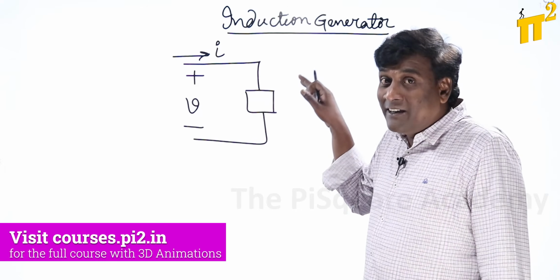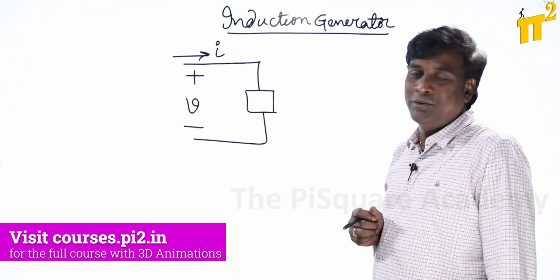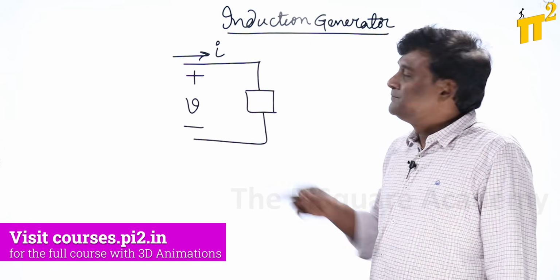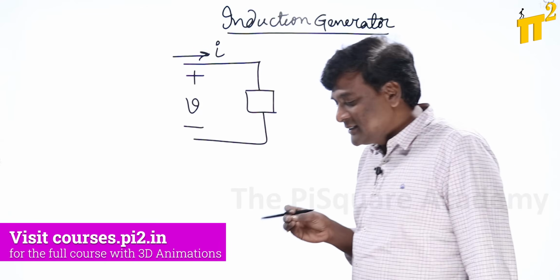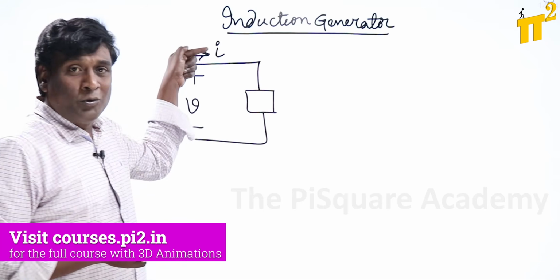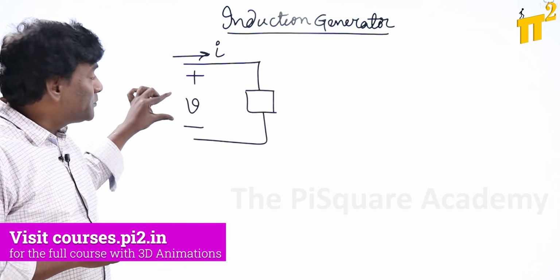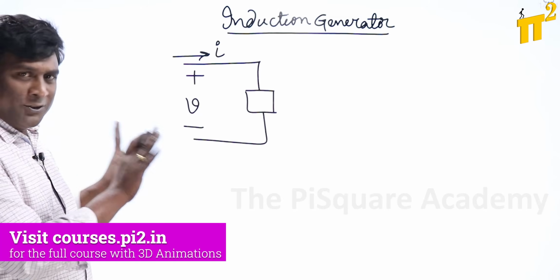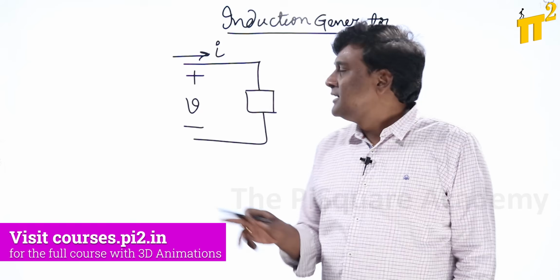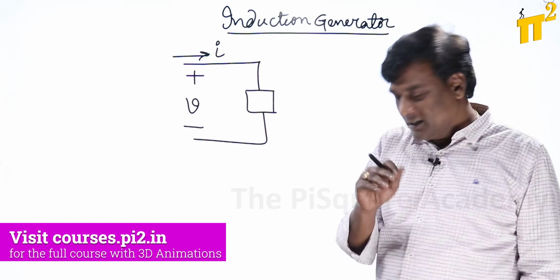Yes, it will definitely absorb power provided these are DC components, but this may not absorb power if it is an AC component. The moment you are supplying sinusoidal voltage to any system and sinusoidal currents are flowing here, the position of current with respect to voltage only will decide whether this particular system is absorbing power or not. Now let us see.